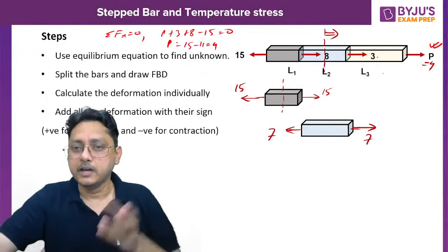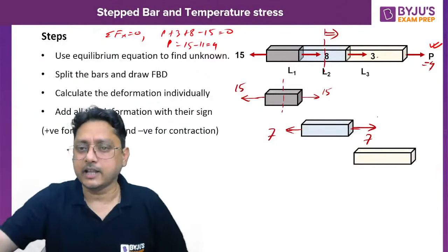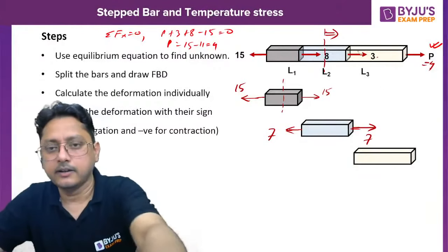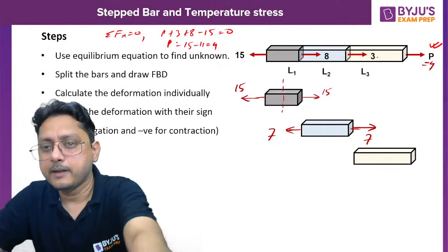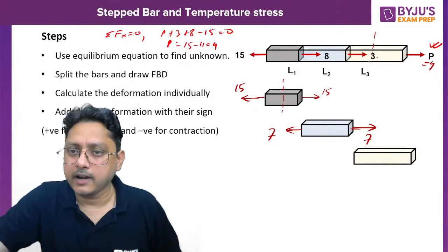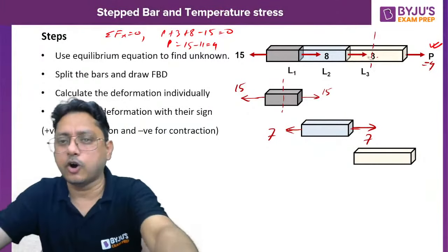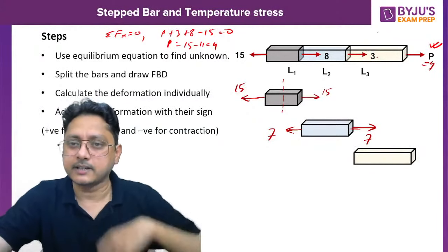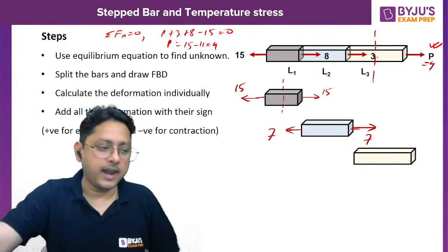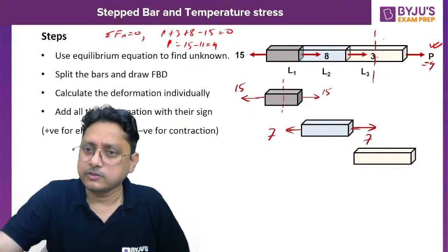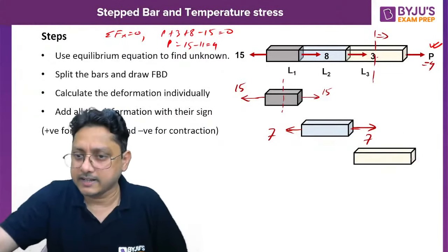That's all. Take the next block. Once again you stand at the center. By standing at the center, you add all the forces either towards the right side or the left side of the considered section. Now, if I add towards the right side, because I have a smaller force here, I will add all the right side forces, which is nothing but 4, acting at this particular block.